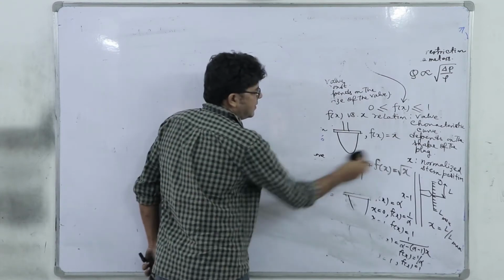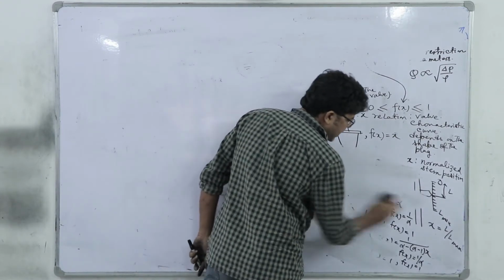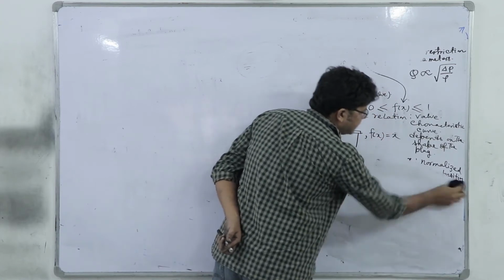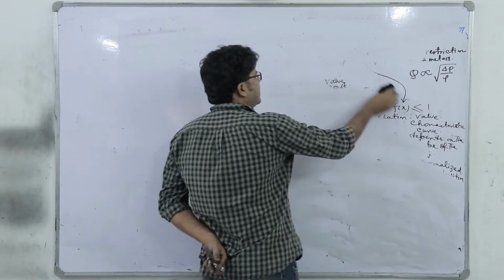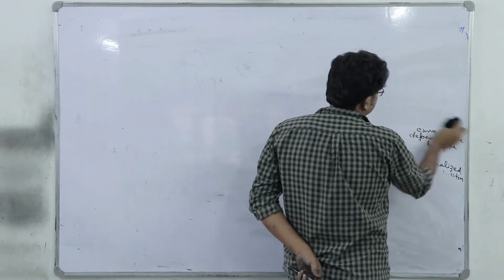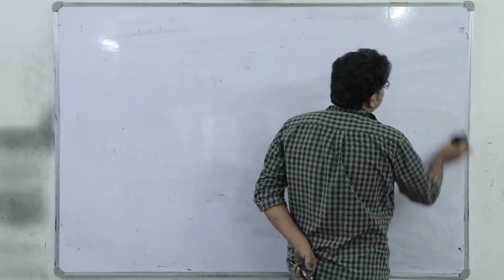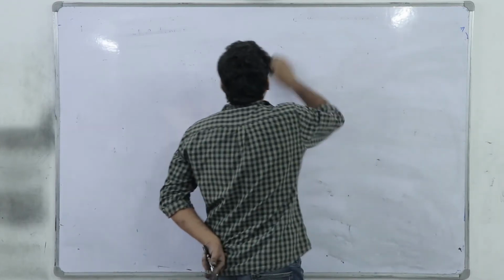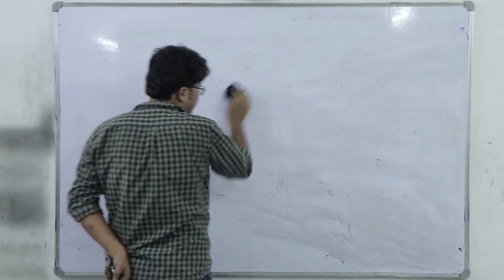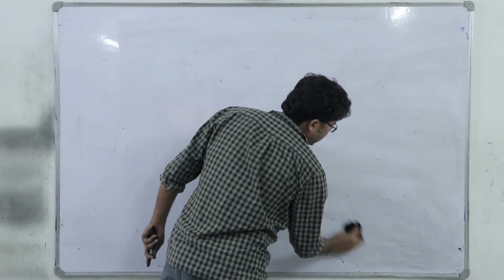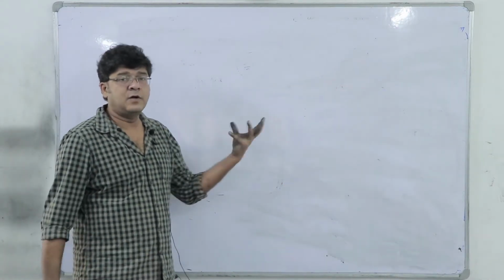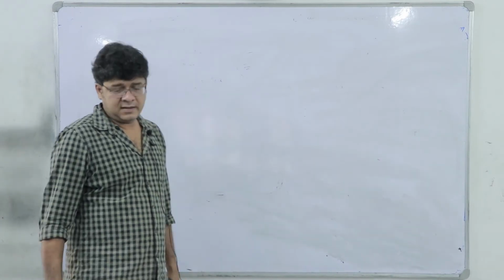And similarly, if C, another characteristic constant of this valve, which is associated with the friction between the fluid and the stem, is negligible relative to the spring constant, the relation between P and X becomes a pure gain element, and as Q and X is also a gain element, overall it is a pure gain.